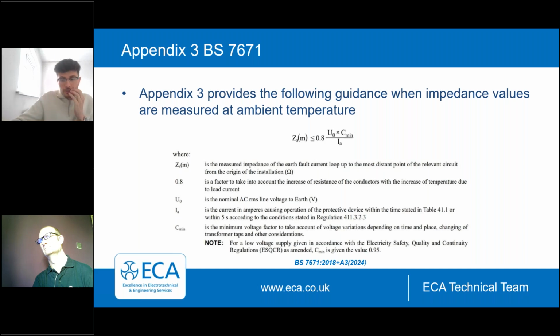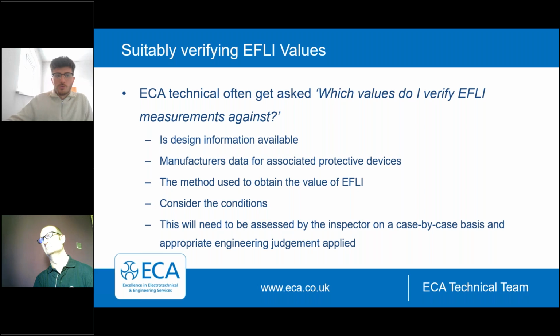So often, particularly when we've got a brand new installation and we've done the R1, R2 method, and added to ZE or ZDB, it's going to be practical to compare against these values because, as we pointed out, circuit loading, or the absence of circuit loading in this case, means that the readings are going to be lower. So that's what that is based on, and that's where those values within the Guidance Note 3 and so on come from.